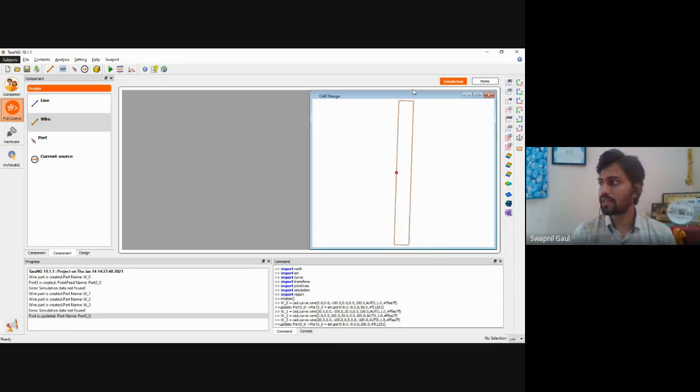If you see the simple dipole antenna, we used to feed it with a coaxial line because the coaxial line has an impedance of 50 ohm only, and the antenna has around 73, and it shows a better match.